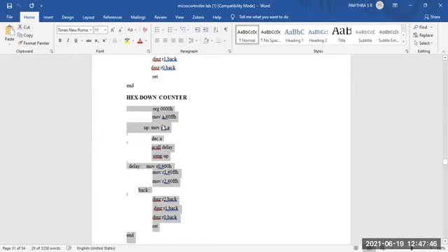We can't keep on checking the register value. That's why we're going to load it onto the port, so that we can observe inputs and outputs on the ports directly. So it will be loaded to the port register, that is the P1 register.